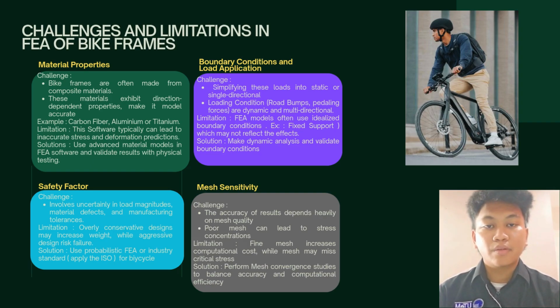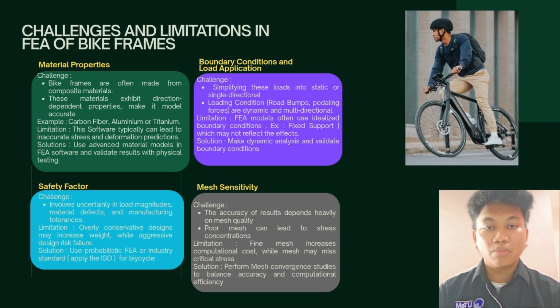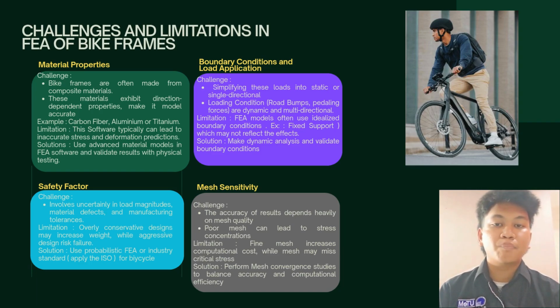Next, the safety factor presents a challenge due to uncertainty in load magnitude, material defects, and manufacturing tolerance. Overly conservative design increases weight, while aggressive design risks failure. Probabilistic methods in FEA or industry standards like ISO are key solutions. Lastly, mesh sensitivity significantly impacts accuracy.